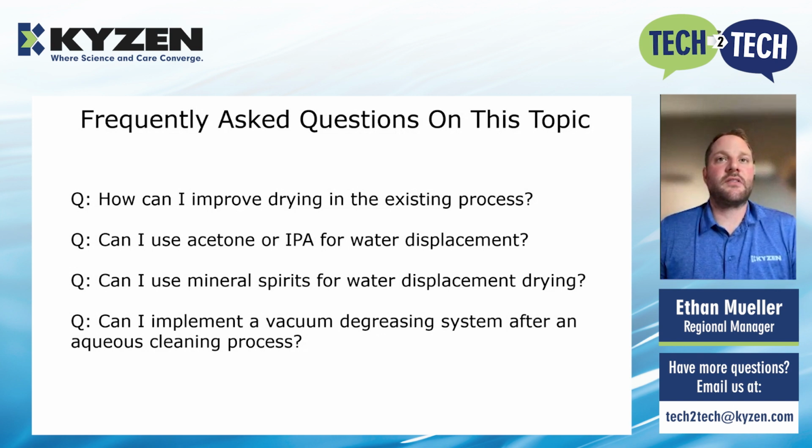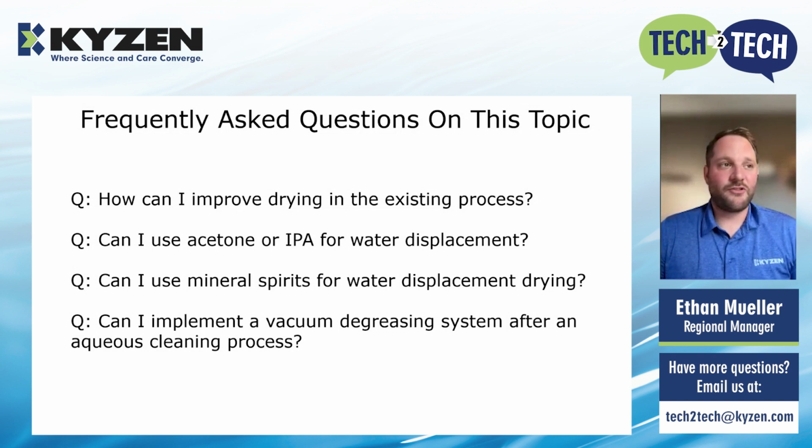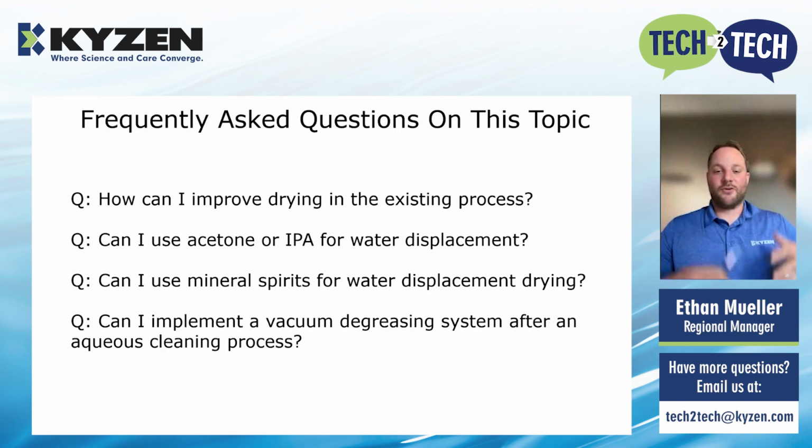Can I implement a vacuum degreasing system after an aqueous cleaning process? I would say in most situations, you could replace your aqueous process with the vacuum degreaser. If you were going to put a vacuum degreaser right after an aqueous process, you'd almost be better off just completely eliminating that. There is some nuance to that, obviously. If you're trying to clean a part that maybe has polymerized oil or carbon or other ionics or oxidation, maybe you do need that aqueous process upstage. But for everything else, you would be doing two cleaning steps to ultimately dry your part. So let's just go with one cleaning step that also dries in the same exact process. And with that, I will turn it back over to William.